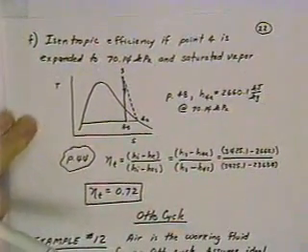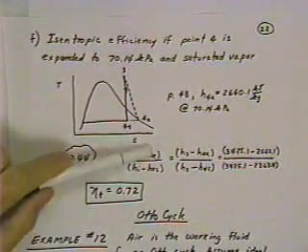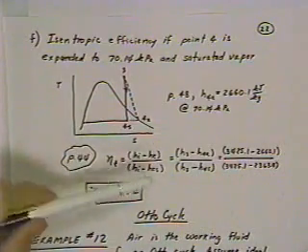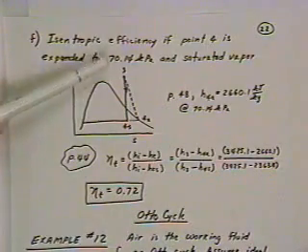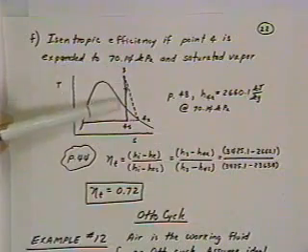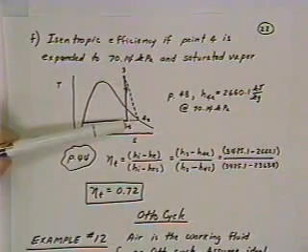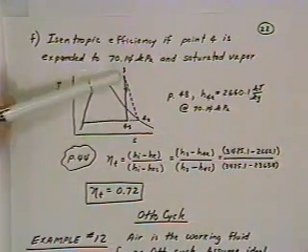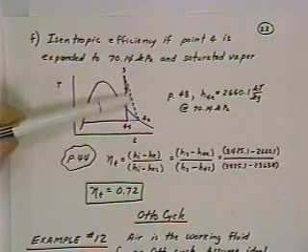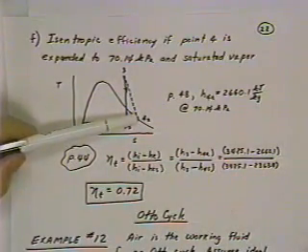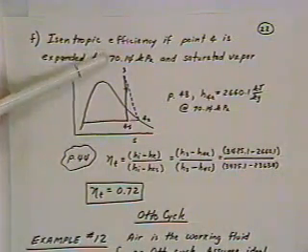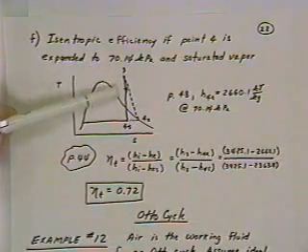So it's efficiency involving HI minus HE over HI minus HES. And so isentropic efficiency says how well does the turbine approach isentropic conditions. And in this particular case, we're saying instead of expanding isentropically and reversibly down to H4s, the expansion really takes place irreversibly down to the saturated vapor condition corresponding to 70.14 kilopascals.